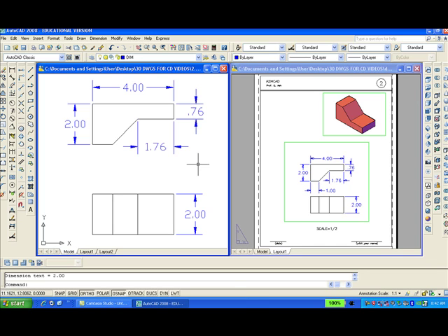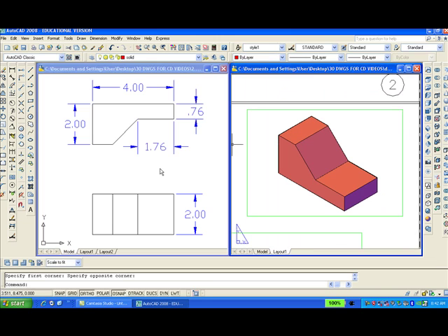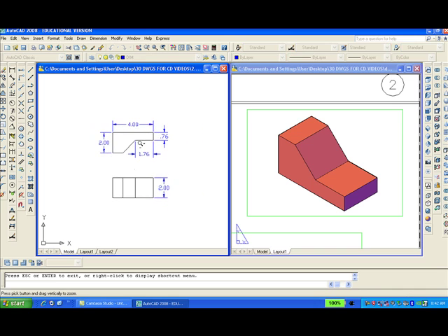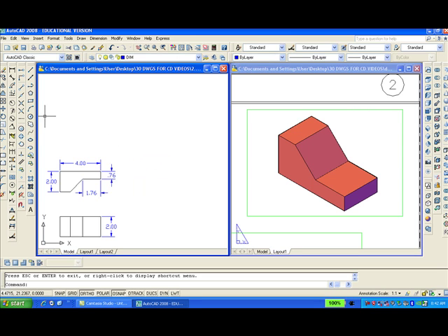Next, I click on the right drawing, right side, and I'm going to enlarge it because we're going to be making this solid model here. So I'll click now on the left screen. I'll use zoom real time to shrink down the drawing. Then I'll pan and move it to the lower left. Now I'm going to use a polyline, which is in the draw toolbar. Here it is here. And I'm going to trace over the perimeter of the top view, like that.